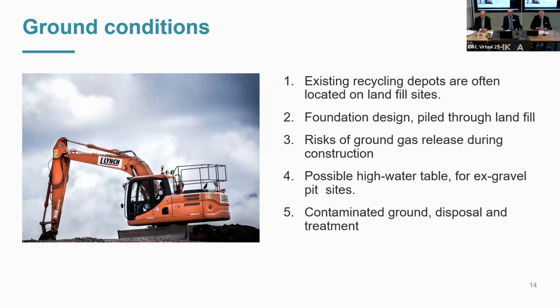Here in the UK, obviously, we have limited ability to do that. And obviously the environmental impact of burying waste and causing methane gas, etc., is a huge risk to the environment, or a huge impact to the environment. So the contractor has to be very careful when he considers bidding for these works in terms of the foundation design. So normally you'll have to use precast concrete piling system through the landfill mass to provide a suitable foundation for the building and support the large pieces of equipment.